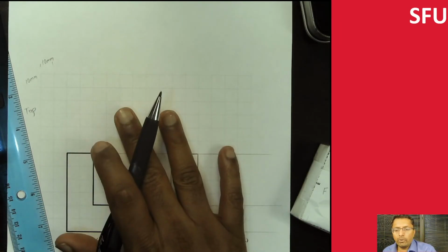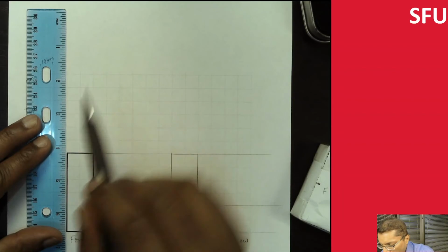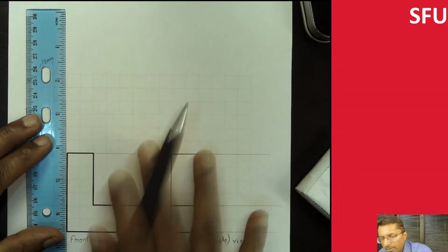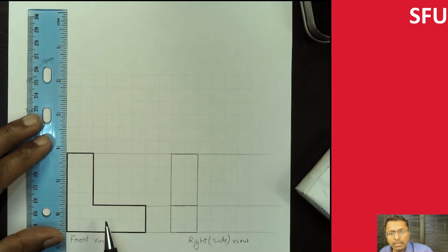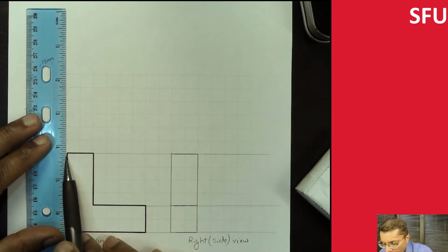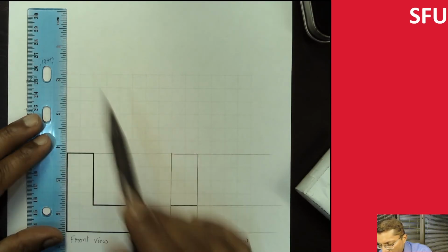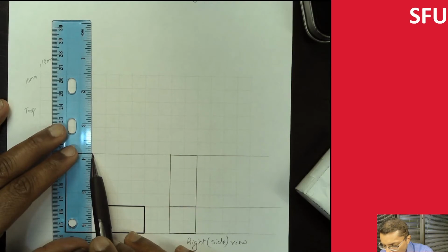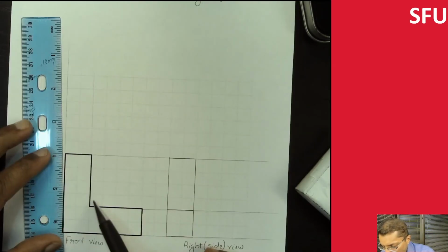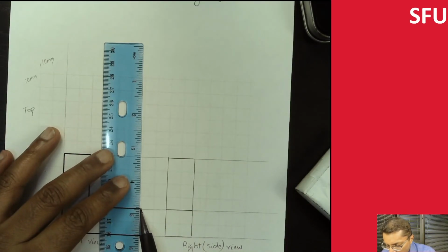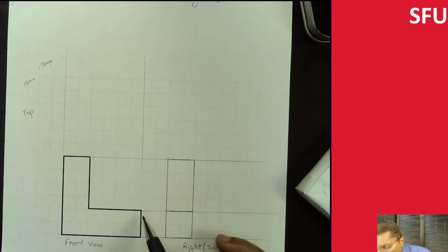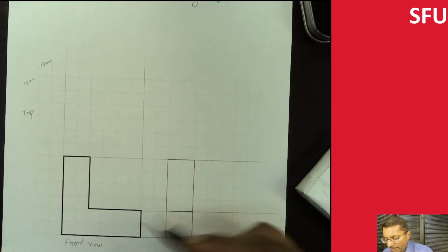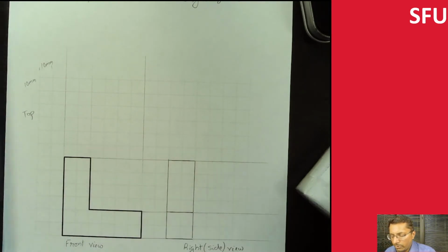So we do the top view. Essentially I'm going to do a similar thing because the top and the front view are going to share the length information. So I'm going to just mark out the length features all over. So extend this, and then this gets aligned here. So we extend this all the way. I do apologize if the lines aren't quite aligned for this particular exercise. We're going to assume they're aligned to the grid lines over here.